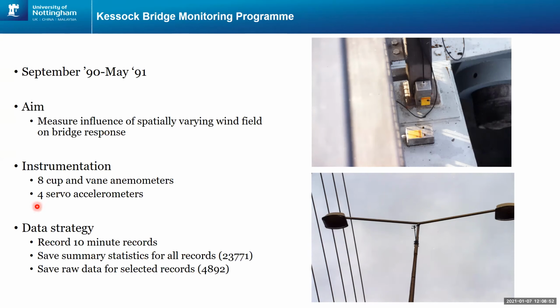And also we were measuring the response using 4 servo accelerometers. We had a very simple data strategy, which is to record 10-minute records, save summary statistics, and then save raw data for selected records. So we've got in total about 24,000 statistics and about 5,000 records of data.